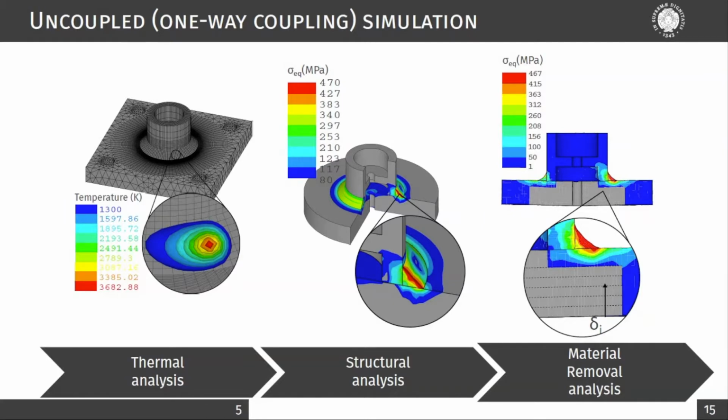First of all, the welding process was replicated from a thermodynamic point of view by calculating temperature variation over time. The welding process was then reproduced from a mechanical point of view through a structural simulation. In this case, the load was obtained as a binary time-temperature data file resulting from the thermal simulation previously solved. At the end of the structural simulation, we were able to collect the results of residual stresses and strains all over the specimen.